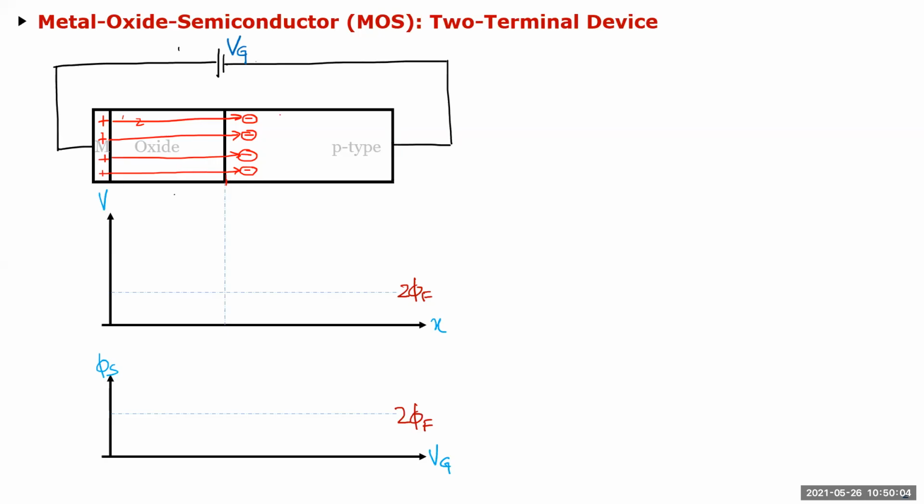Even in a CMOS process, you get what's called parasitic BJTs. So you always get NPN, PNP structures, like the band gap we use for a constant voltage reference. In those we use BJTs. They are not very good BJTs, but they're good for voltage references. There are also a lot of BiCMOS processes. Bi basically says it's BJT plus CMOS, so the process is such that you can have high quality BJTs and CMOS.